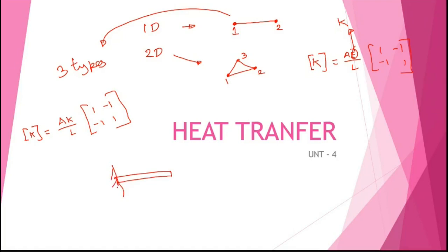One side has a high temperature, and on the other side you identify a temperature without any convection. That is one type, pure conduction. Next, conduction and convection at the ends. Third, the fin problem, where you have convection everywhere, here and also at these points. So we have more convection here. This is your fin type of problem. These are the three different types.